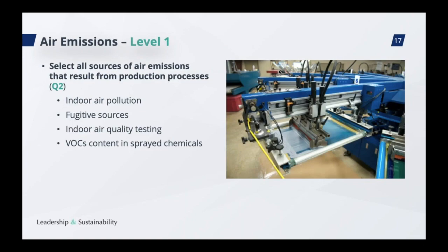Yes. But you need additional information to calculate the annual indoor air emission inventory. You will need airflows of windows or doors, but it's hard to determine. In this case, you can make an assumption for airflow. For example, the total air in your facility changes 10 times a day. So now you have airflow data to calculate the amount of air emission you cause. Now you need to multiply the measured concentration with the total volume in the building and multiply with 10.